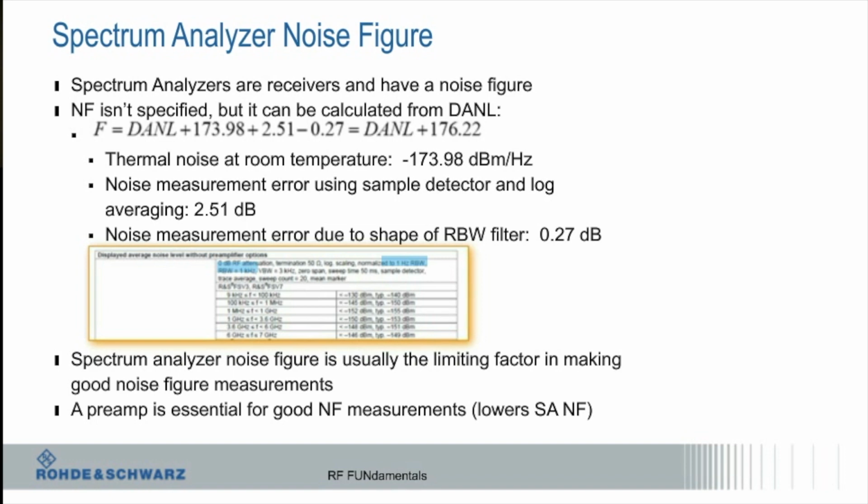But basically, if you say, I want to put in an 802.11a signal, and I want to look at the constellation at the output, and tell me what's the error vector magnitude or whatever, it can do that, whereas a VNA will only tell you what the sine response is. So essentially a network analyzer has a transmit and receive, whereas a spectrum analyzer is just receive. That's correct. But also a network analyzer will only look at a sine wave. No modulation, no nothing. Good question, though.